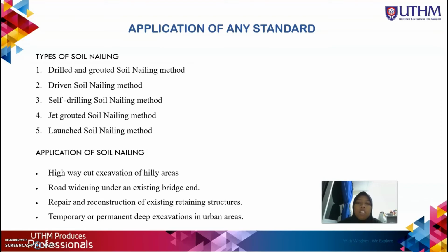Fifth, launched soil nailing method. The steel bars are driven into the soil with a single shot, utilizing a compressed air mechanism in this method of soil nailing. It is used to support an unstable, possibly stable soil mass.